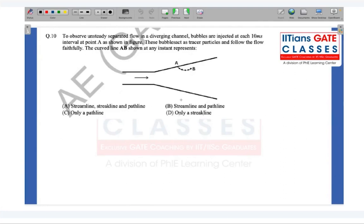So if you look at what these points represent, these are nothing but the location of bubbles that have been injected through point A. So basically, these are nothing but the streak lines of all the fluid particles that have once passed through this point A. So in this case, the correct answer here is only a straight line, and it cannot be a streamline or a path line, because it's an unsteady flow, so you cannot really say that streamlines, streak lines, and path lines are the same.